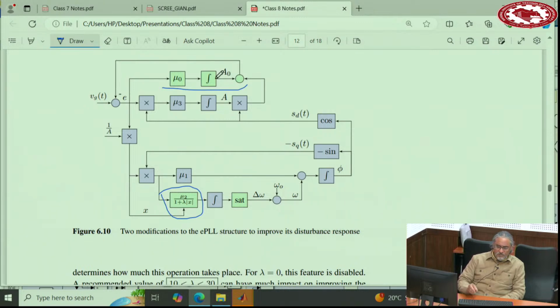The reason is because whenever you want to implement something using digital control, you measure things with sensors, you bring them within the range, plus minus 2 volts or something, and then in order to bring it into the microprocessor, you need to shift it up.